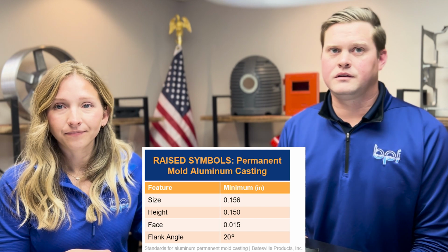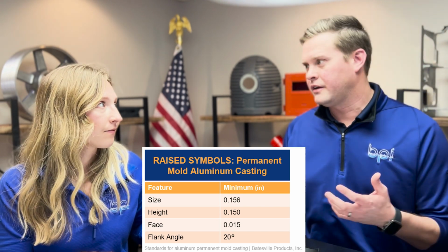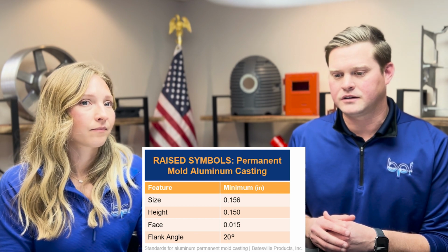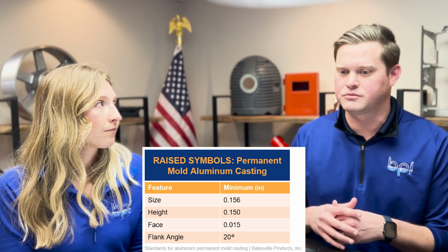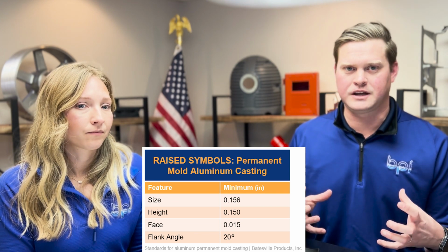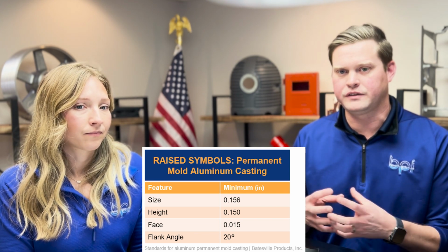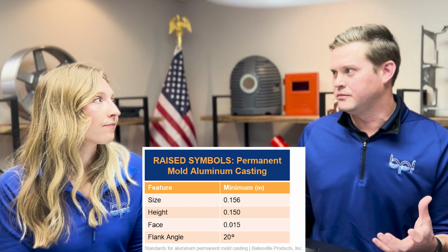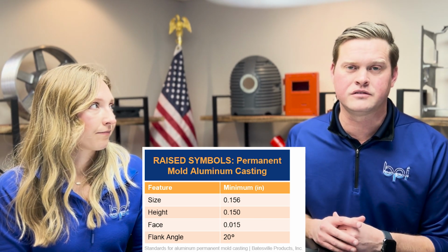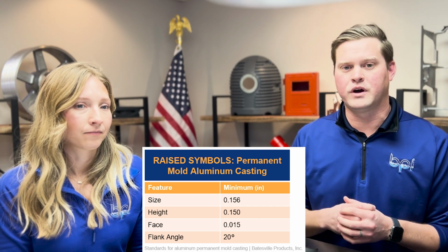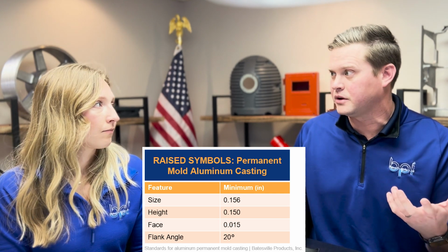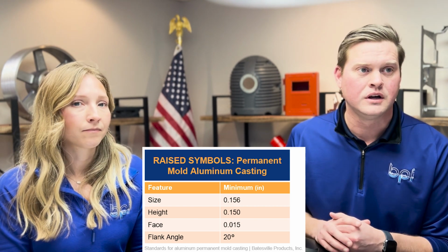Yeah, I mean, this is another great process for adding logos. Any kind of logos, verbiage, words, numbers, whatever it ends up being. The best thing about the permanent mold is we could create these as inserts. So even as the mold wears, we're still holding tight tolerance. If the logo wears a little bit faster, we can go in, remove the insert and replace it. It's a cheap cost to do so.